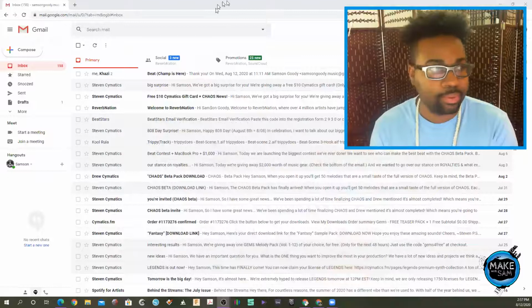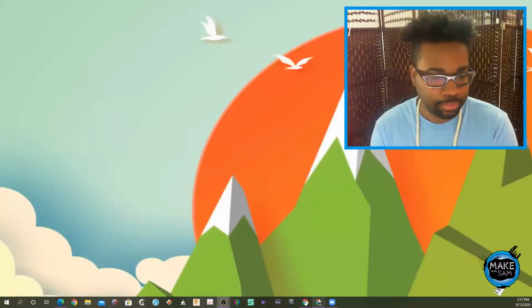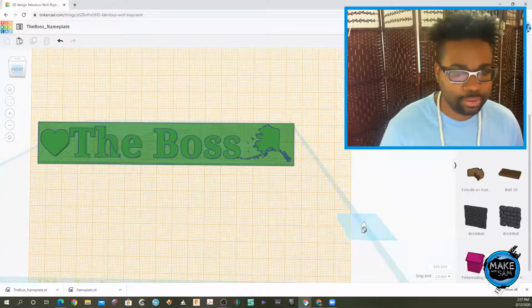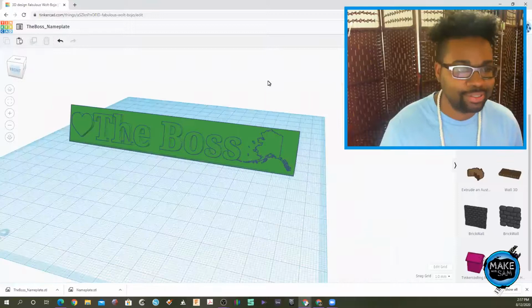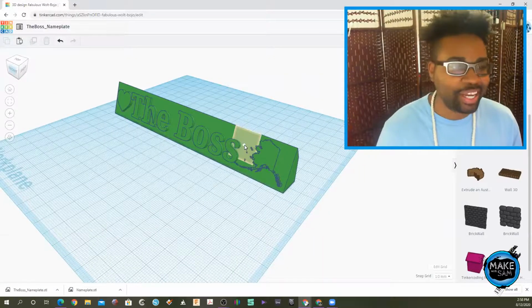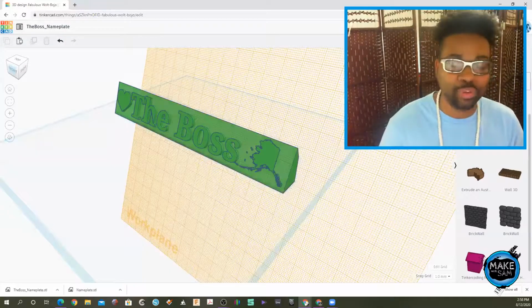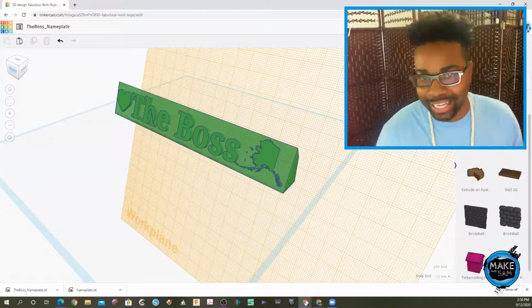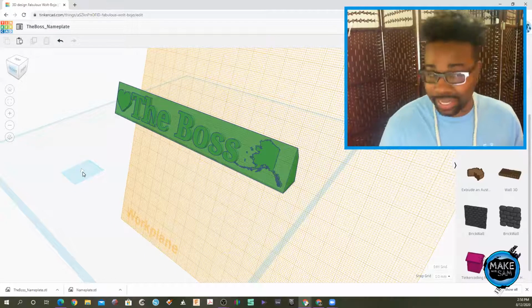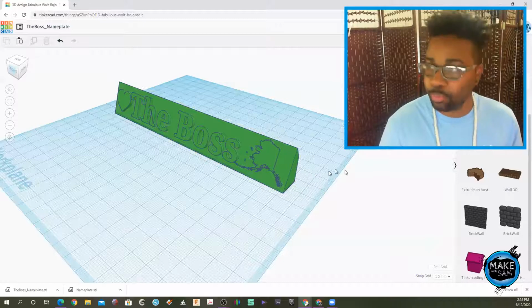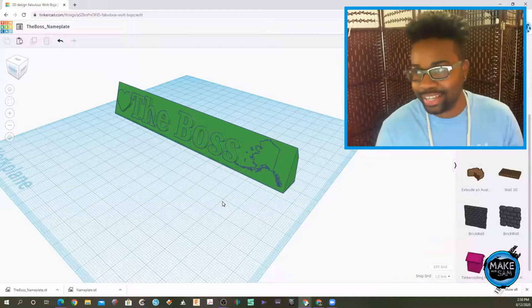I was curious. Okay, work plane. You just click back on the other one. That's all it was. If you want a new work plane on a surface, you click on the surface at that angle. If you want to take that away and go back to the original one, you just click back on the surface where the work plane was. That's it, y'all. We figured it out.